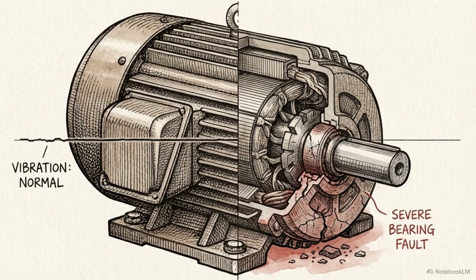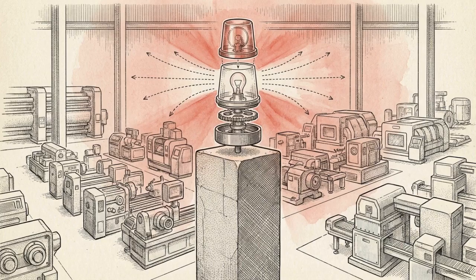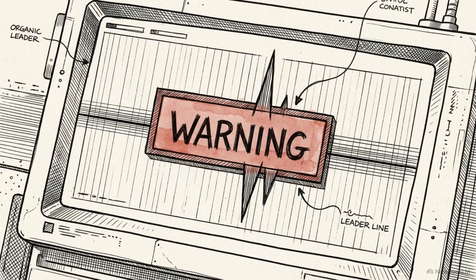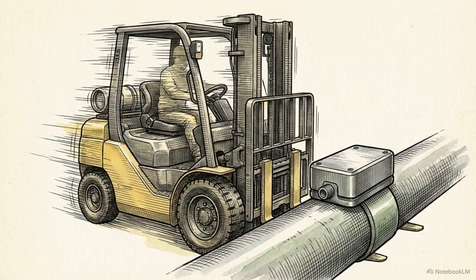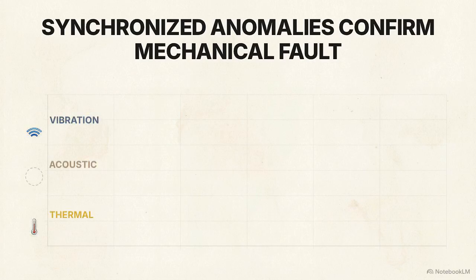Relying strictly on a single signal type to predict equipment failure creates significant blind spots for predictive models. In early predictive deployments, a major structural risk is the frequency and high operational cost of false positive alarms. A single modality, such as a solitary spike in vibration data, easily triggers an erroneous alarm due to overlapping environmental noise or a temporary shift in operational load. Multimodal fusion resolves this ambiguity by integrating multiple sensor types into a cohesive analytical model.